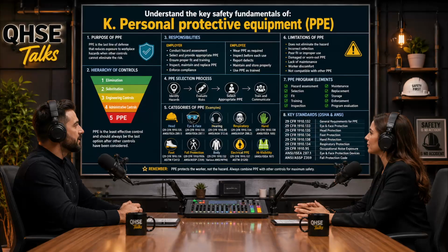So if a hazard analysis determines a potential arc flash could generate 10 calories of thermal energy, the worker's FR clothing must have an ATPV rating of at least 10, right? Preferably higher, like the 12 cal/cm² baseline, often required for specific switching tasks. And the fabric acts as a thermal shield, absorbing and dissipating the plasma heat before it can transfer that 1.2 calories through to the skin.